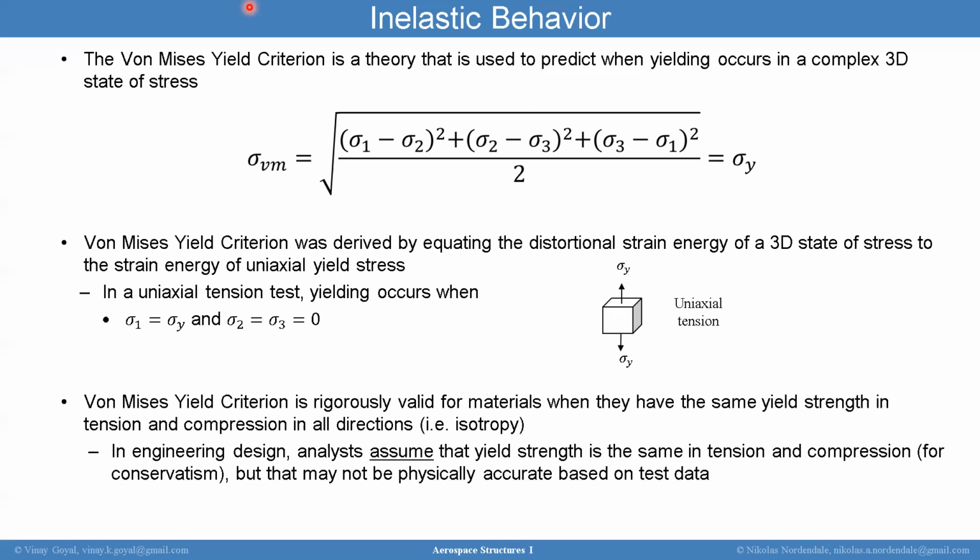Also for weight savings could be useful, right? Yes, definitely. If you are assuming your compressive strength is lower than it is, and your part is predominantly loaded in compression, then you probably want to take advantage of the actual material strength, not just a conservative assumption.